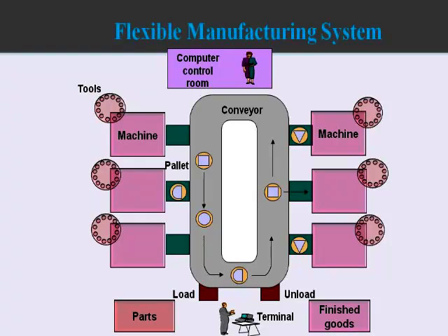Suppose a tool is broken. Once the tool is broken, the machine gives a signal to the controller that the machine is in a breakdown stage due to the tool failure, and a human operator is required who can come and change the tool at that time, replacing it with a new tool or any other used tool. He has to do it, and he needs to do presettings.